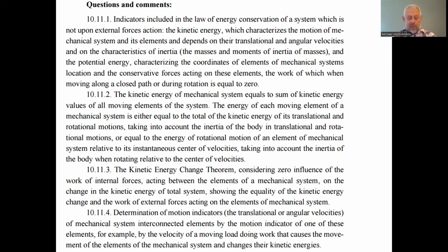10.11.3, the kinetic energy change theorem, considering zero influence of the work of internal forces acting between the elements of the mechanical system on the change of kinetic energy of the system, showing the equality of the kinetic energy change and the work of the forces acting on the elements of the mechanical system. That is true if we are not talking about elastic bodies. For rigid bodies, stiff bodies, solid bodies, we consider only the external forces.